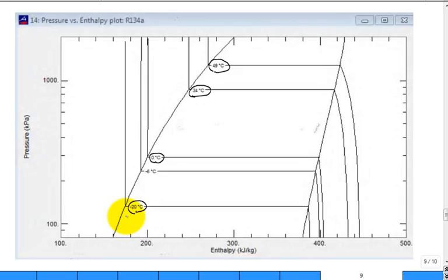And then the mixture at state 1, after that expansion valve, it was negative 6. Okay, so I want you to sketch a pressure enthalpy diagram knowing these values of temperature and put the states on, okay? I'll give you a minute.